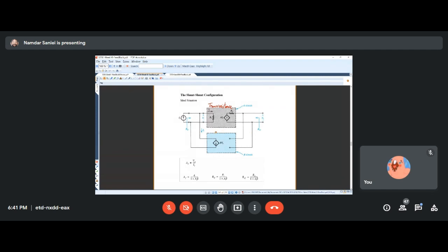Yes. So shunt, we had parallel on both sides, input and output, which meant both input resistance and output resistance must be divided by 1 plus A beta. However, the gain is always A over 1 plus A beta, except this gain now is a trans-resistance amplifier. So it is a gain of the voltage over a current. This is true for the loop. Whatever the loop demands, which is a voltage over a current, it follows this formula, same formula for all of them.